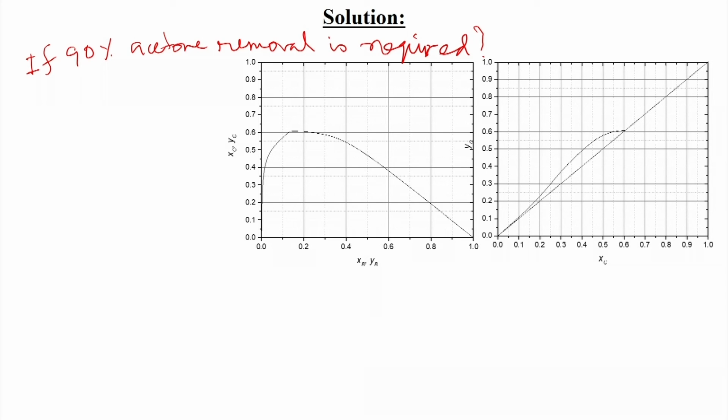Now, we are assuming that the mutual solubility of water and chlorobenzene is negligible. So, solvents A and B are not mixing, we are neglecting that part, and we can say that the raffinate phase is free of water. Whatever R1 is there, only chlorobenzene is there, that is what we are assuming, but in reality it may not be the true case, as the chlorobenzene may contain some amount of water.